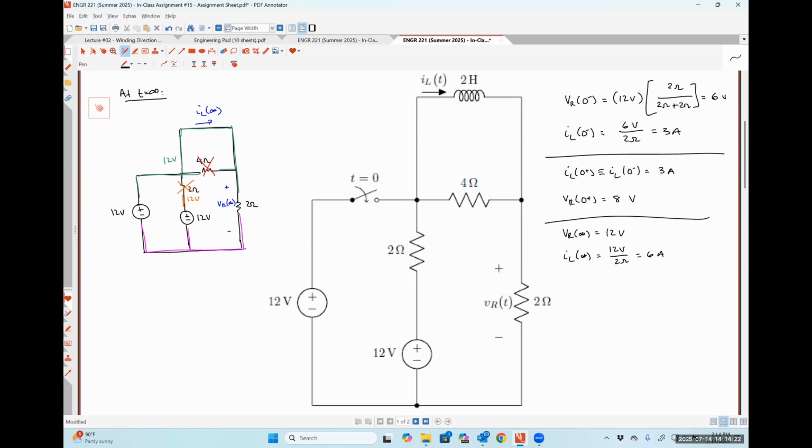If we wanted to do a more formal nodal analysis for this guy, we could, but I think we'll wind up getting the exact same results. Actually, we can't do a more formal nodal analysis because we have 2 supernodes, each of which touch ground. So really, if we wanted to do this a different way, we would have to wind up doing mesh, which I'm just going to trust that I'm right.